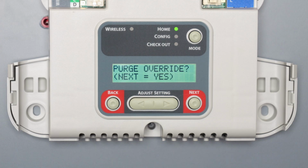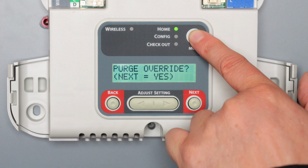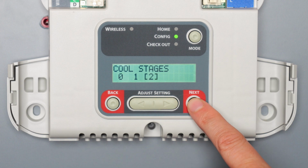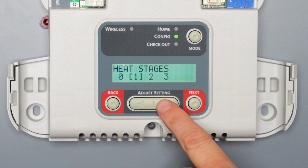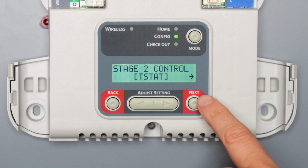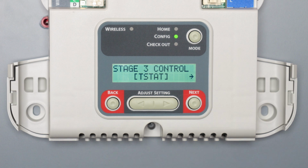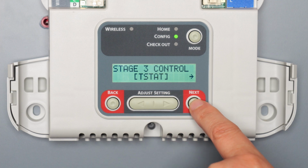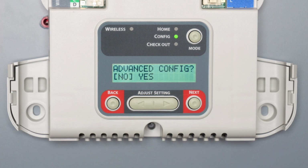To begin programming the zone panel, press the Mode button until the LED for Config lights up. After you've selected your system type, number of stages of cool and heat, and the number of zones installed, then you will see the Stage 2 control options. Use the Adjust Settings arrows to select TSTAT and press Next. If you have a third stage, you will then see Stage 3 control. Use the Adjust Setting arrows to select TSTAT. Press Next and continue with the configuration of your zone panel.